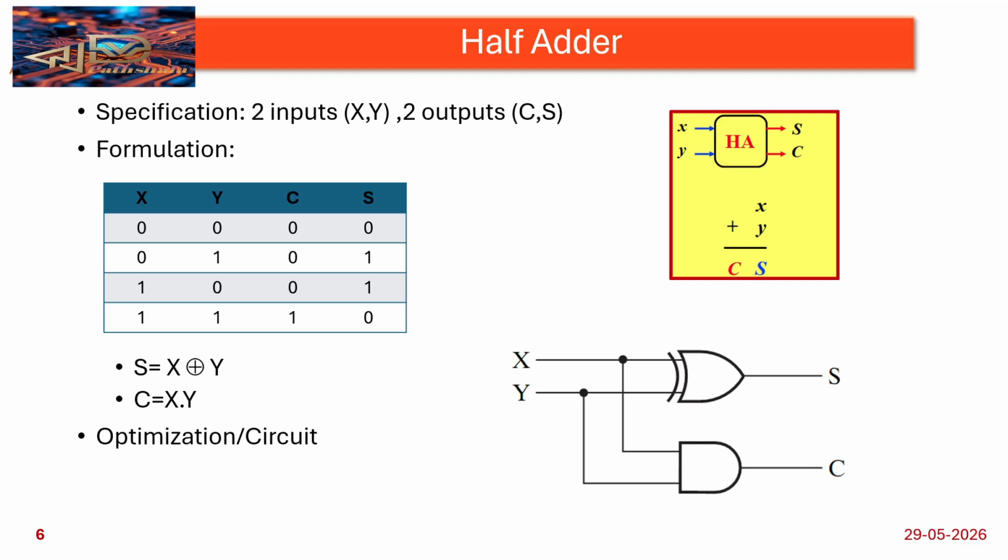First, we will go through the half adder code. Before that, we'll start with what a half adder is and what equations we need to write. So this is the truth table. This truth table defines what type of outputs we are getting and what type of inputs we are applying. Here x and y are the two inputs I'm considering.